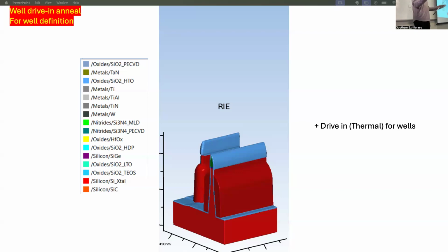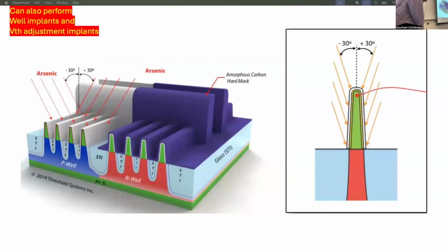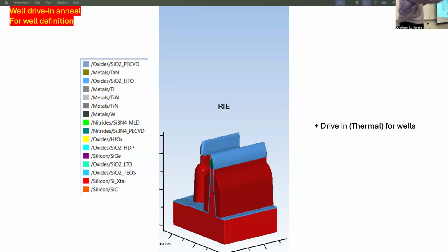And the value of the doping that you need to calculate is based on how much threshold voltage you want, right? The same way you calculate for this. Yeah, if we were to use ion implantation, that's the next thing. So there's an alternative way to do it. Remember here, because you're using diffusion, it's going to dope this uniformly all the way around, right?